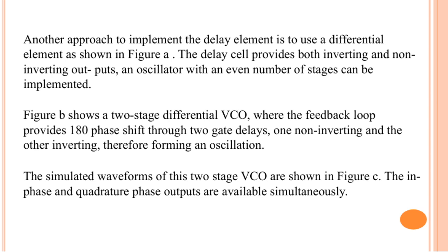Finally, Figure C presents the simulated waveforms for this two-stage VCO. Notice that it simultaneously produces outputs that are in phase and in quadrature phase, which is particularly useful for applications requiring these signals in parallel. This setup highlights how the use of differential delay elements can effectively simplify designing even-stage oscillators.